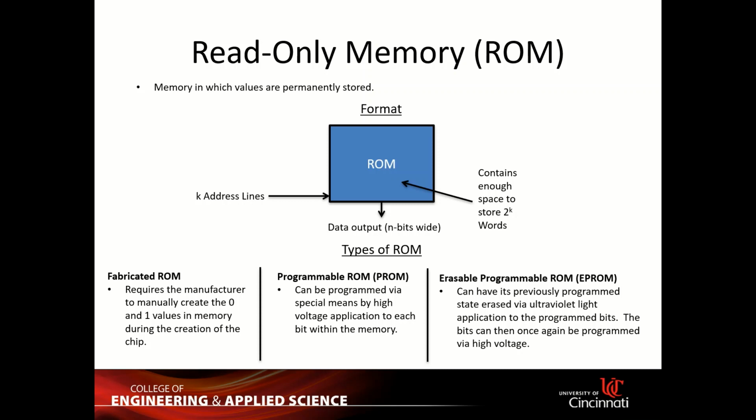So Flash suffers from that too. If you read and write maybe 1,000 times, 10,000 times, I don't have a number in my mind, probably let's say 100,000 times, if you read, write, and erase it a lot, it just stops working. It's time to move on.